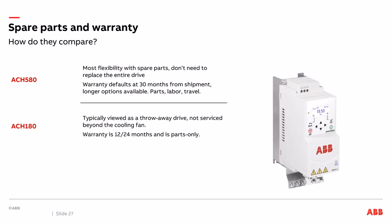The ACH180, those compact, those micro drives, they're typically viewed as a throwaway device. They're not really serviced. They don't troubleshoot them a whole lot other than the cooling fan. The very small ones don't have a cooling fan. Bigger ones do, so the cooling fan can be replaced. But other than that, the control panel, it's integrated to it.